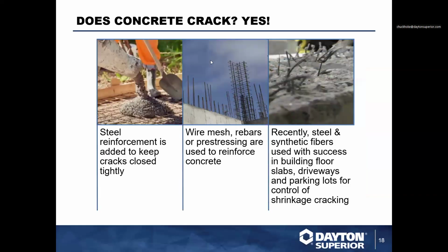Does concrete crack? Yes. That is why we typically add steel reinforcement within it. The steel reinforcement, wire mesh, rebar, etc., is designed to help hold the concrete together. Sometimes there is also pre-stressing. Pre-stressing is where they actually squeeze the concrete slab once it cures a little bit, to squeeze everything in and help increase the compressive strength of that concrete.